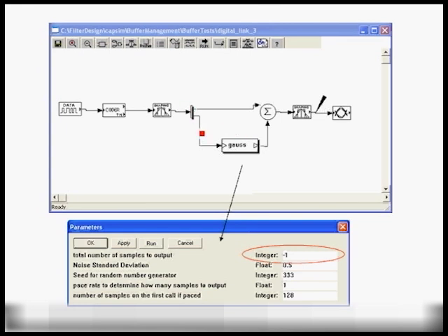The way we do this in Capsim is we actually design source blocks to have what you call a pacer at the input. Actually, the data block also has that pacer, but if it's not connected, it ignores it. The Gauss block, if in fact an input buffer is connected, then it would pace itself to that input buffer, and instead of indicating to the Gauss block how many samples to generate, because we really don't know, that's governed by the block, the B data block here. That's where we want to tell it how many bits to generate in a digital communication link.